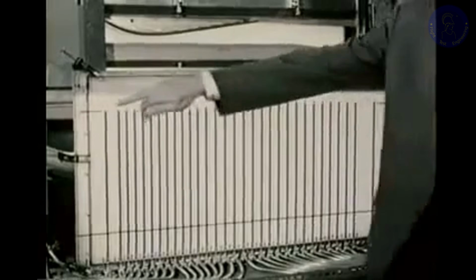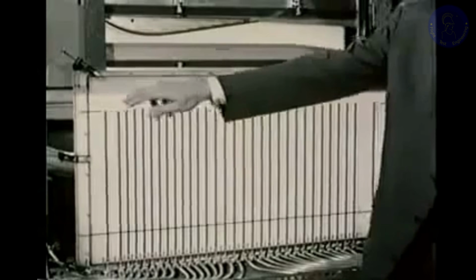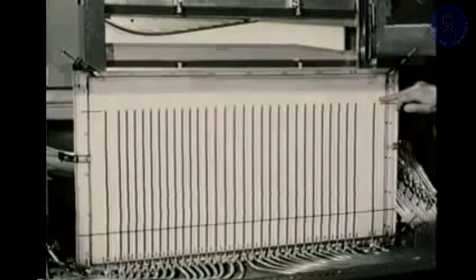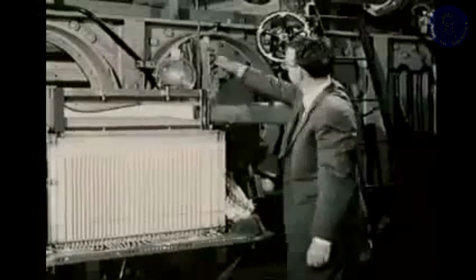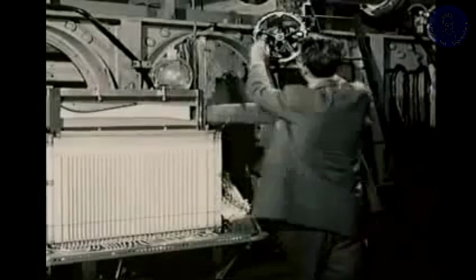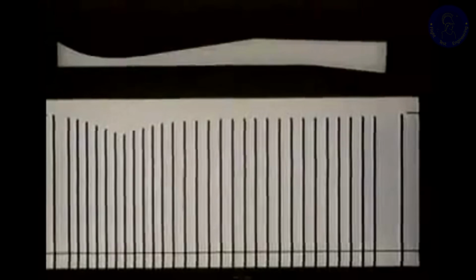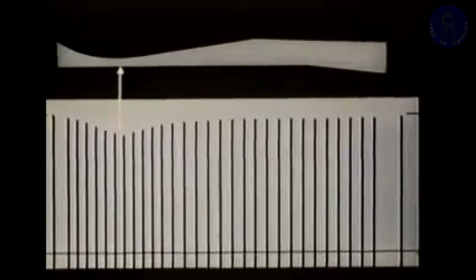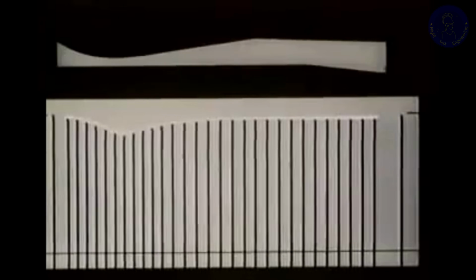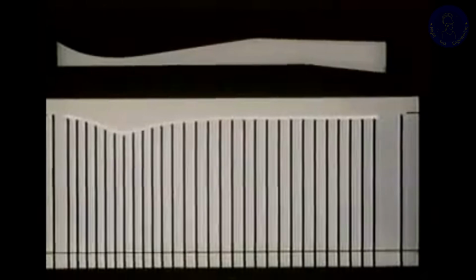The first column always shows the stagnation pressure upstream, the pressure in the room. The last column always shows the downstream stagnation pressure, just ahead of the valve. At low rates of flow, the pressure is nearly symmetrical around the point of minimum area, called the throat. We can draw a continuous pressure distribution and interpret the curve qualitatively as velocity.